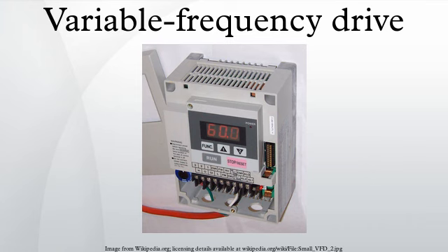Long lead effects. The carrier frequency pulsed output voltage of a PWM VFD causes rapid rise times in these pulses, the transmission line effects of which must be considered. Since the transmission line impedance of the cable and motor are different, pulses tend to reflect back from the motor terminals into the cable. The resulting voltages can produce overvoltages equal to twice the DC bus voltage or up to 3.1 times the rated line voltage for long cable runs,